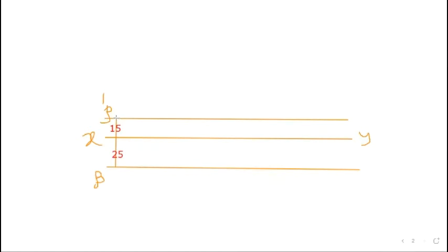So here at this point we draw a 45 degree line and measure 60 millimeter. So suppose this is Q1 dash. So P dash Q1 dash will be 60 millimeter and this angle will be 45 degree.